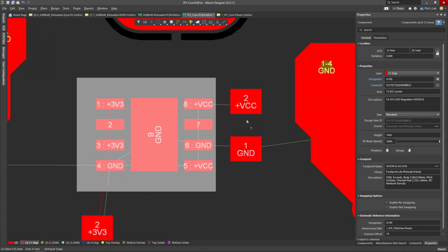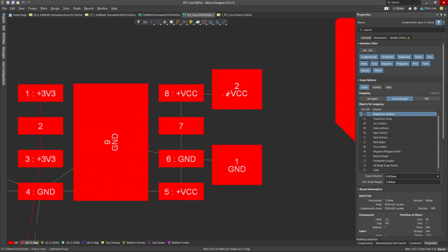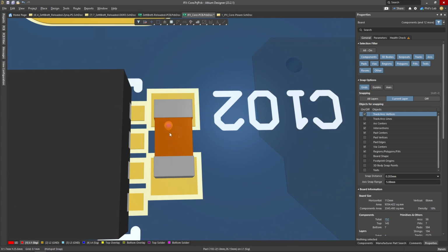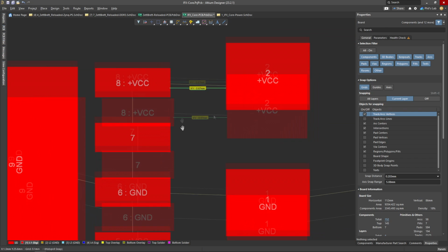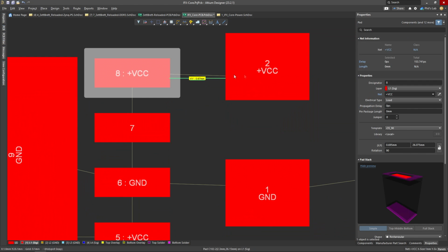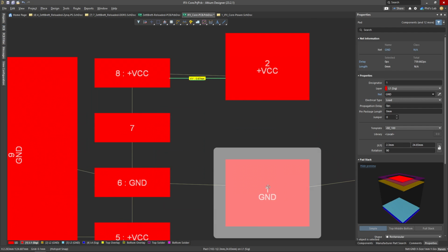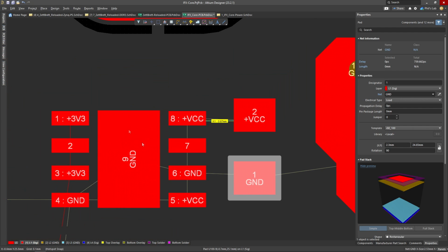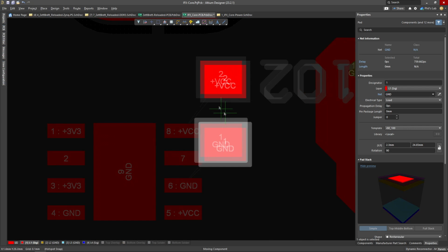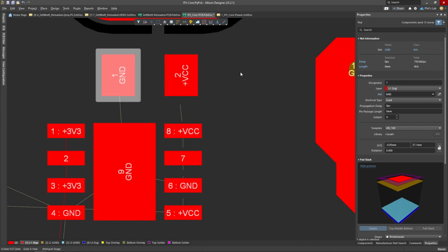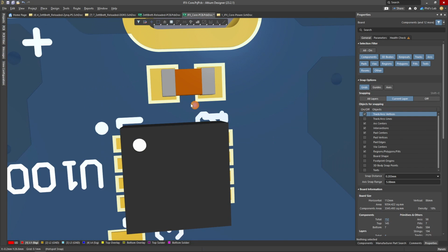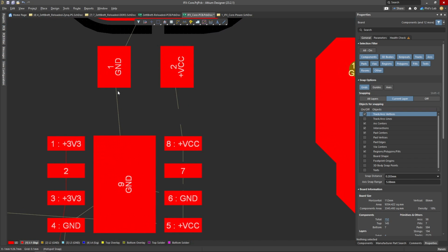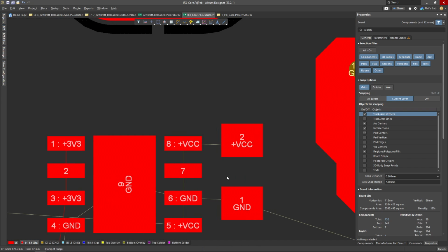and therefore I can either place my input capacitor like so, not like so, because this is very, very minimal space. Assembling this, of course, won't work, so we need to move this a fair distance apart, but still close enough to the device. In this case, this is less than a millimeter, and we have nice straightforward connections from pad 8 to our capacitor and pad 6 to our capacitor. Alternatively, because this has an exposed pad in the center, which is also grounded, we could place our bypass capacitor like so, maybe moving it slightly further away, something like this, for example, very crudely done. This might be a less ideal situation, so I prefer a connection, for example, something like this.